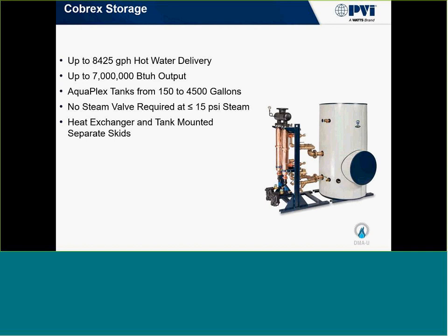So with regard to that heat exchanger, what we can also do is incorporate a storage water tank with it. And this is where we start getting into sizing things differently. Traditionally for an instantaneous steam unit, you're going to design that system for your max flow. So if you require, let's say, 120 GPM of flow, that's what you have to size your steam side requirements for: your steam side piping, your heat exchangers, and everything else.